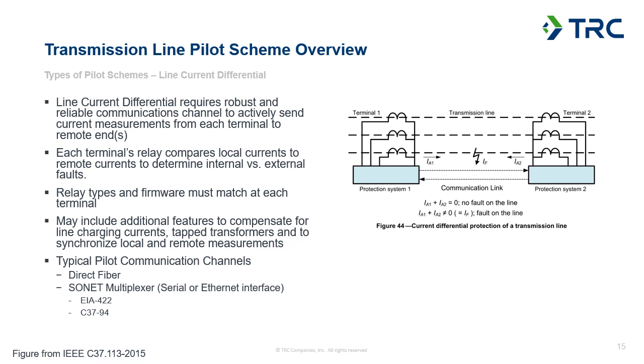So the last type of pilot scheme we're going to talk about today is one that's really starting to be used a lot more commonly on the transmission system, primarily due to the increases in availability of a more robust communications channel, and that's line current differential.